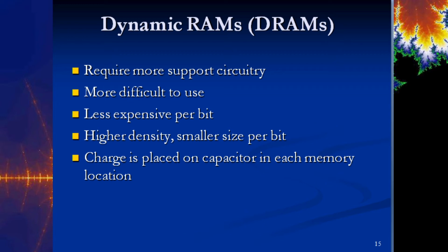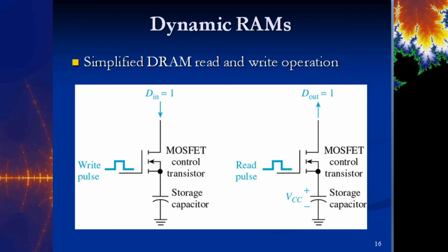Well, I should say it's quicker to change the transistor, turn it on or off like a switch, versus the capacitor, which has to charge and discharge. So for instance, if you wanted to write a 1 to the storage capacitor that we're using here, right now, and until we get this pulse on the gate, this is isolated from everything, until this shorts out with a pulse.